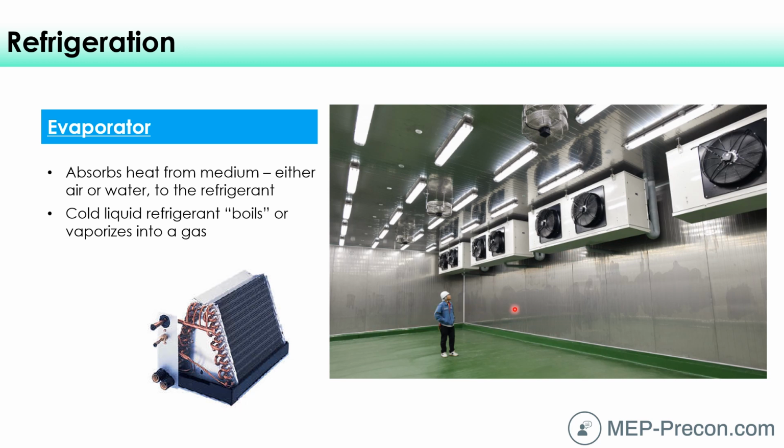It could be a freezer or a refrigerator, but that's where we pump out the cold air, or essentially we're removing the heat from this space through the evaporator. And where does that heat go? Well, it's going to go out through pipes to the condensing unit. And that condensing unit takes all those BTUs from the space, and dumps it out of the building, exchanges heat to the ambient air. So within the evaporator, that's where the refrigerant boils into a gas form.